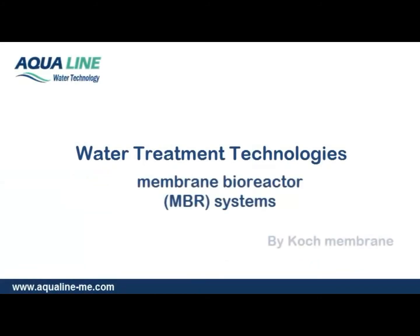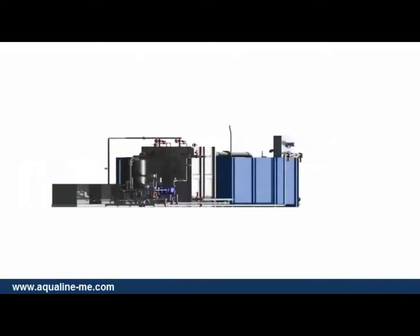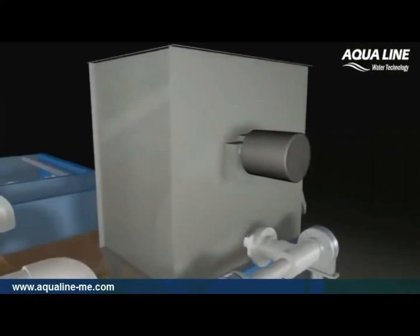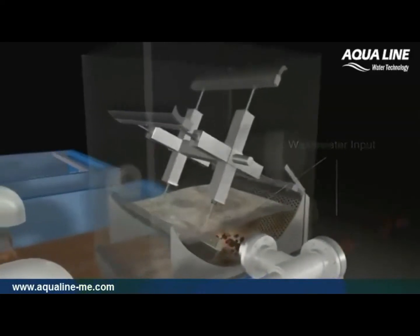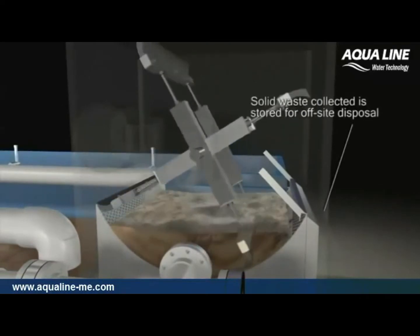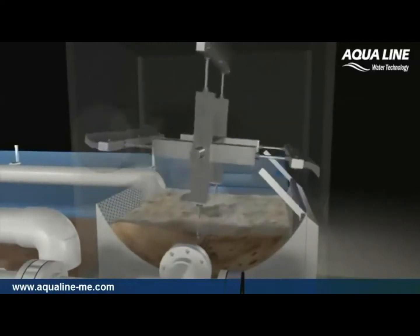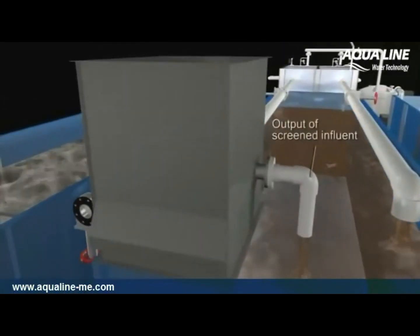Membrane bioreactor, or MBR, is an efficient and cost-effective product for treating municipal and industrial wastewater. The first step of the treatment process is the mechanical screening of the incoming wastewater. The wastewater enters a screen that is equipped with a 2 to 3 millimeter perforated plate. The solid particles or screenings are retained and continuously removed from the screen unit for disposal. The screened wastewater flows into the anoxic tank.